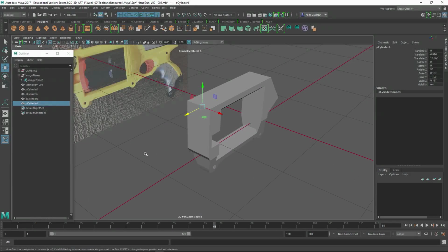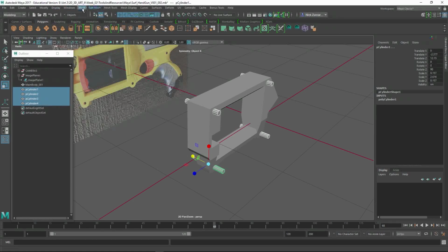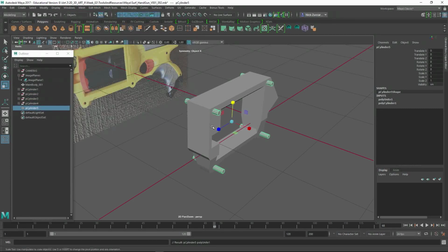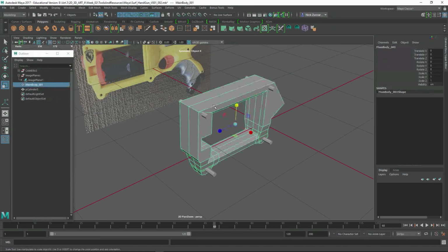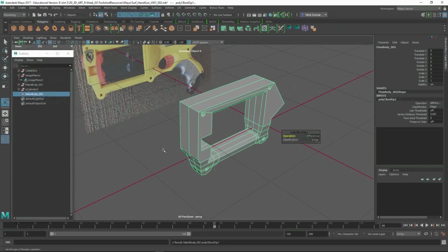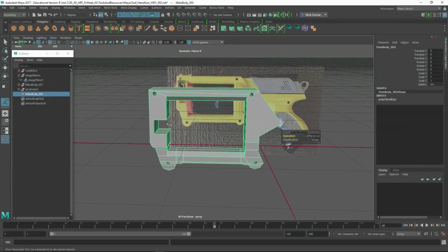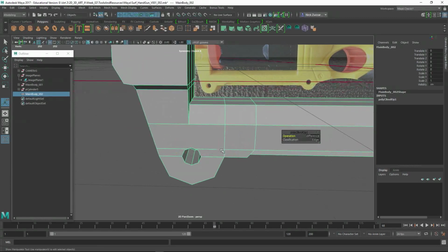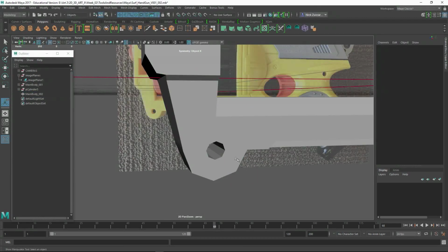Now let's take a look at these cylinders, right? We can scale them out like that. And then we'll do a modeling operation. We'll combine them together, delete the history, and remember we did the difference between these guys. I'm going to save real quick, just in case. Get this object, hold on Shift, select these, and then we're going to go to Mesh Booleans and do a difference between those two. And so now we've got some holes in through here. It does a pretty good job.